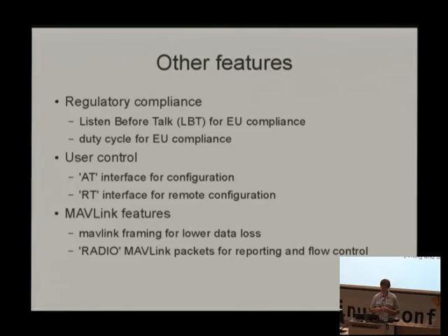Duty cycle for EU compliance, where you can transmit at much higher power if you only have a 10% duty cycle, and there are very strict rules on calculating that duty cycle, which is how often you transmit. As I said, the AT and RT commands are very useful. We also, because we now had control over the firmware, could start adding additional protocol features.